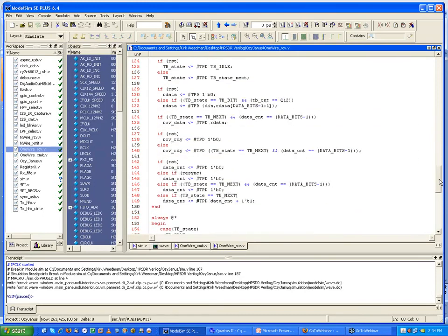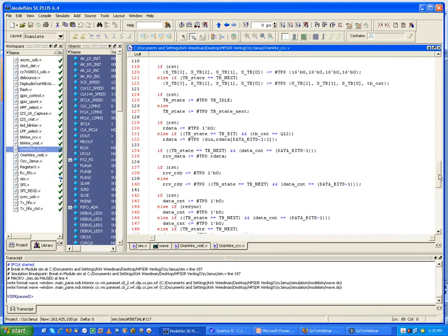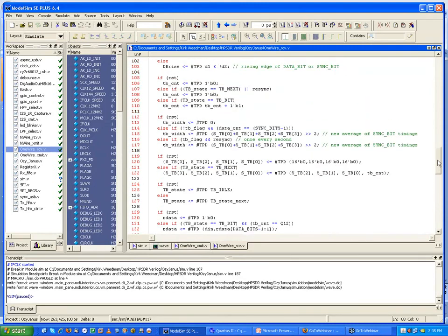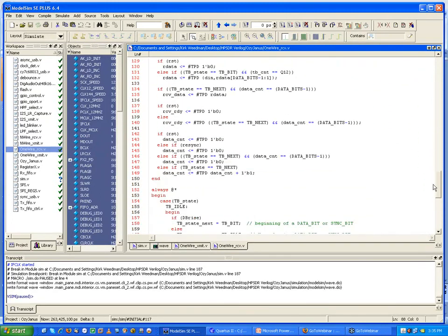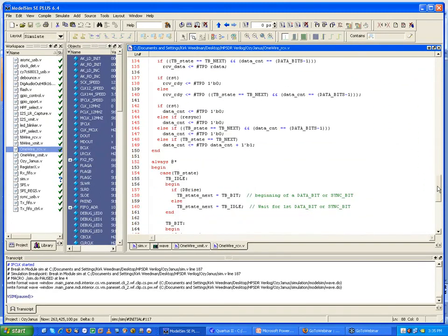So anyway, I have this block. And you'll notice that within this block I have different variables that I'm creating, and each of these are using non-blocking assignments. So that's the key, that these get turned into flip-flops, this basic structure. Like I said, we're going to cover more of this in the lab.